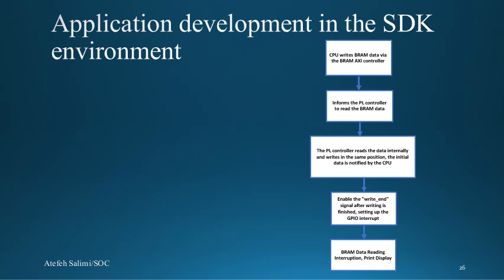For example, here we have used Vivado 2018 version 2, because of that we have SDK in this Vivado tool. What if you use the newest version after 2019? You don't have SDK anymore, and you will encounter the Vitis environment, which is very similar to SDK.